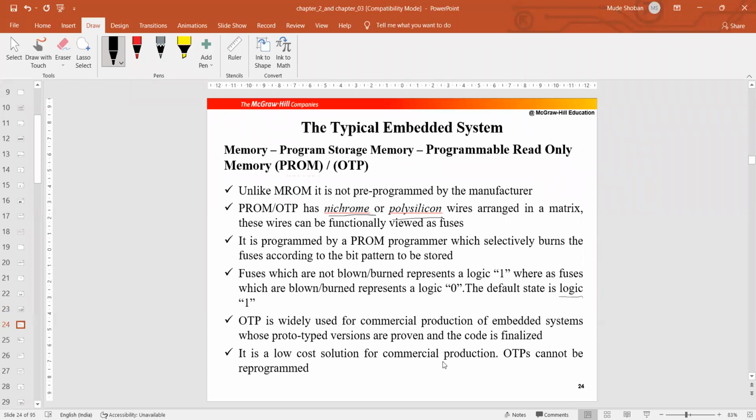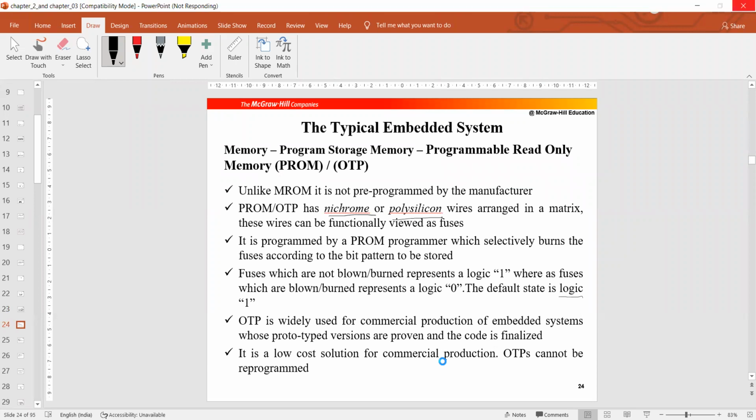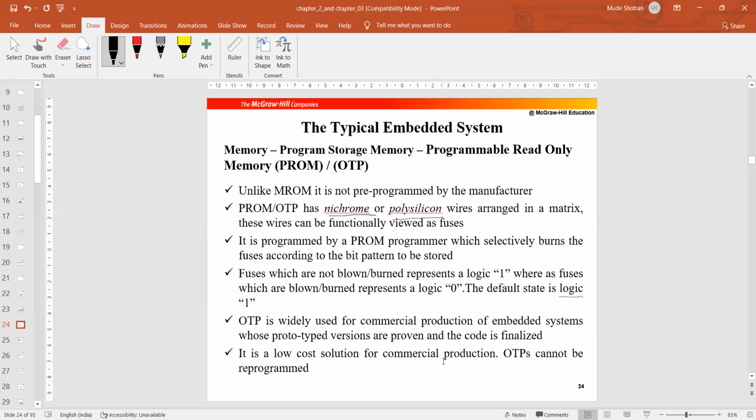And this is the programmable read-only memory, PROM, right? See, how you can store the data: the device you are using is a semiconductor itself, right? Say a transistor, NPN or PNP, or a CMOS device may be used for storing. Even for 1 bit, flip-flops, JK flip-flop, D flip-flop. Each flip-flop has the capability to store a single bit of information.